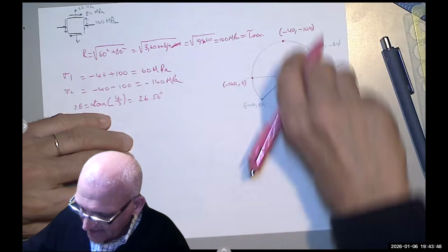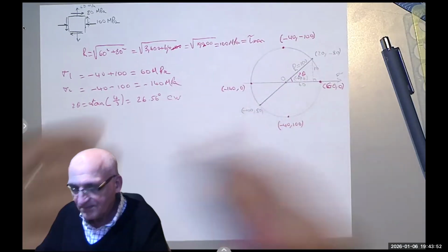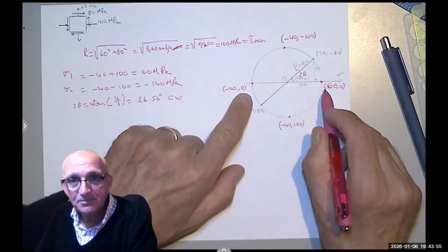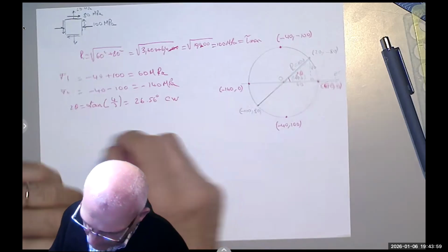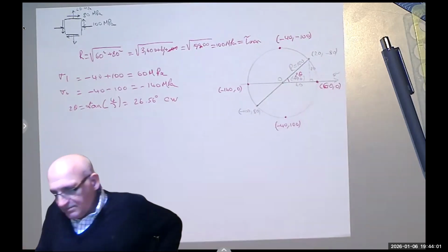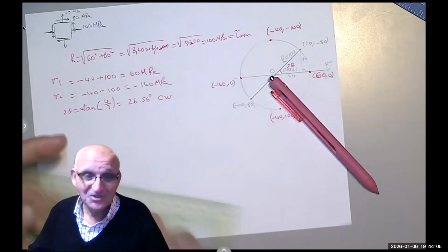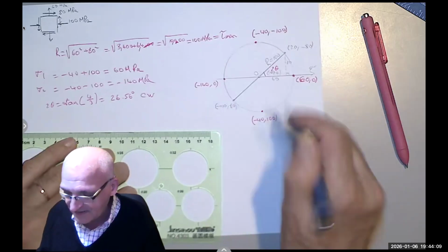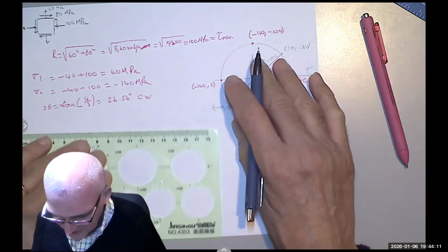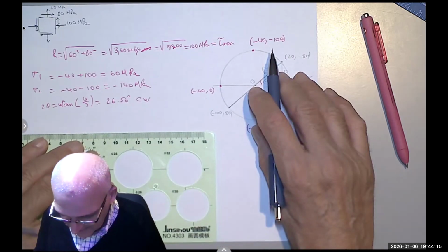It's the same, but this time I have to rotate clockwise to reach the principal stresses, not counterclockwise, okay? So in order to draw that, I'm sorry guys, I used the same ratio, 4:3. I could have made that 3 and this 4. So at least the angle would have been the complement of that.